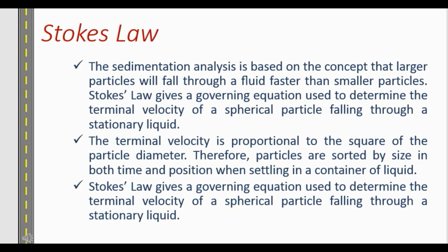This test is based on Stokes' law. The sedimentation method of particle size analysis is based on the concept that larger particles will fall through a fluid faster than the smaller particles. So the whole test is based on Stokes' law. Here some points are provided regarding Stokes' law.